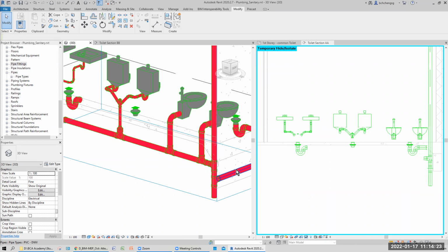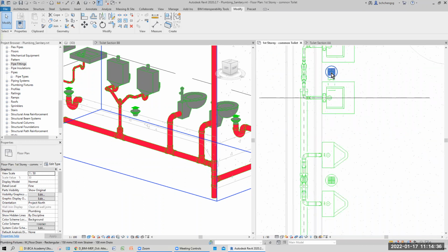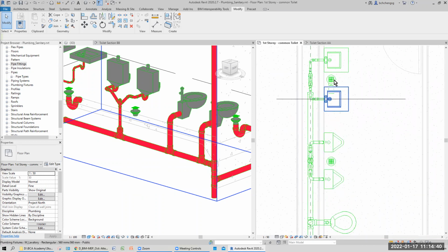So basically up to you. You want to try sloping? You might say, sure, in this case, where should I start the sloping percent? Now, in your plan, you got to track exactly the center here, right? So I will say that from this edge here, snap to here.